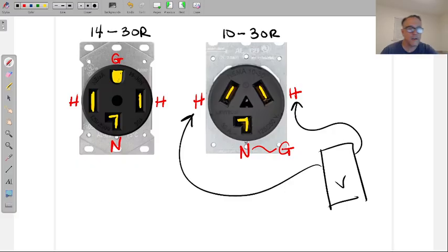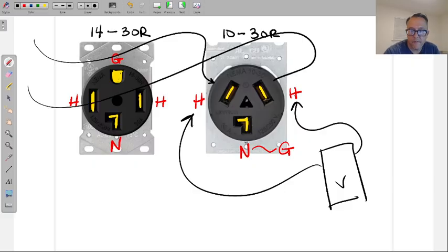No funny business in the breaker because it's just kind of hard to do that inside of a panel. Panel has fixed bus bars and can't really move things around. But as I was saying also yesterday, somebody could potentially run a single phase breaker to here, another single phase breaker feeding this one. They happen to be the same from an A phase position on the breaker on the panel and from the A phase position on the panel. And now when I measure across the hot here, I'm not going to see 240. I'm going to see 0 or something, again, something weird from the meter.